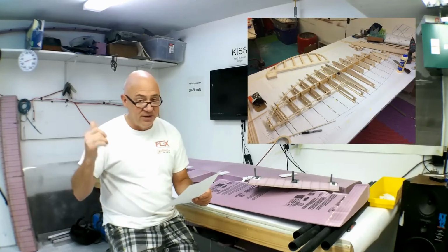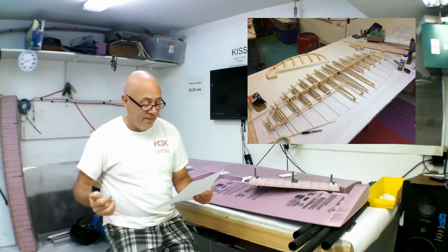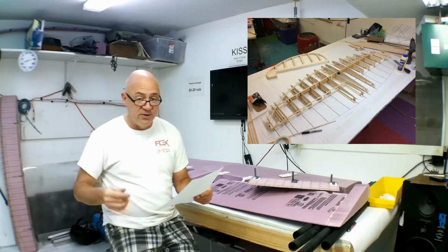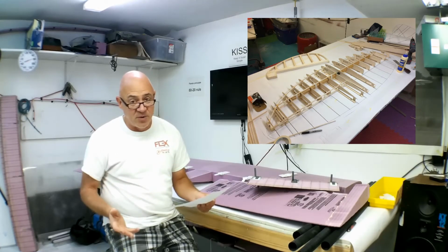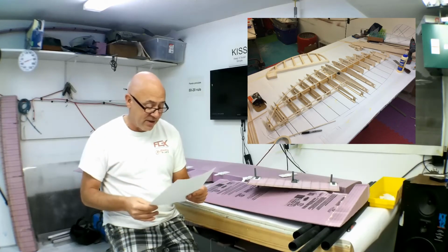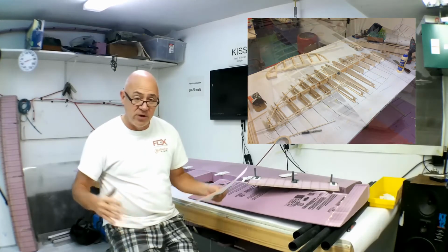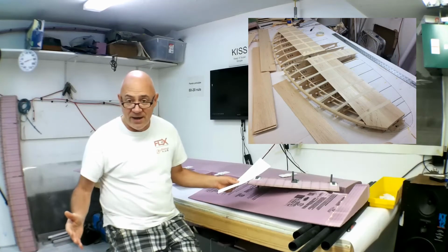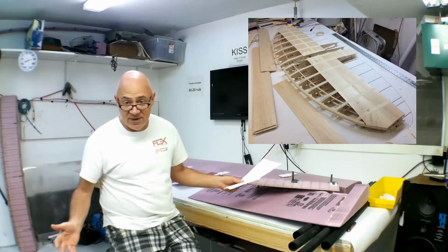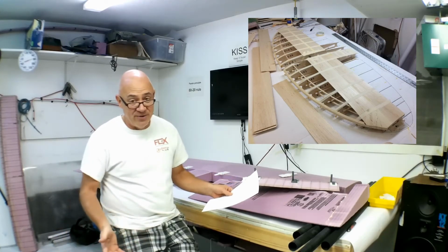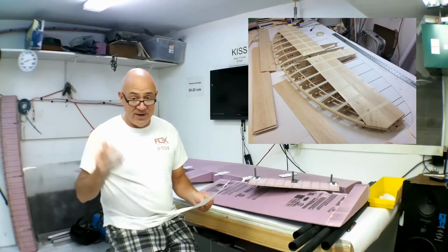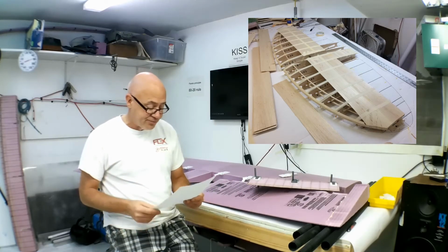Type of construction: is it going to be built up or is it going to be foam? Type of spar used. Basically, you've got to think about how you built the spar for the wing. That's what you want in a horizontal stabilizer. Removal of the H-stab. Does it need to come off? If your trailer is only an 86-inch opening like mine, and you build a 96-inch horizontal stabilizer, it's not going to go in and out of your trailer. So you're going to need to say, do I need that to come off?